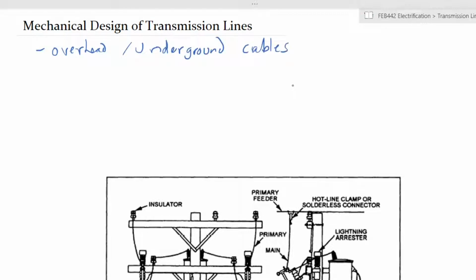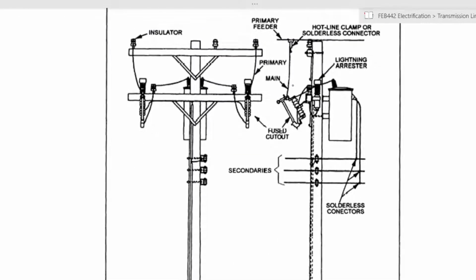In the case of overhead, they generally look like this. This is the pole mounting of transmission lines. Usually, you will have either a 3-wire or a 4-wire system. Most commonly 3-wire systems, as we had said last time, in transmission and distribution, all the way down to 11 kV. And usually the 4-wire systems would be the direct lines to consumers. So whatever consumers will be receiving at their supply will be usually in 4 wires.